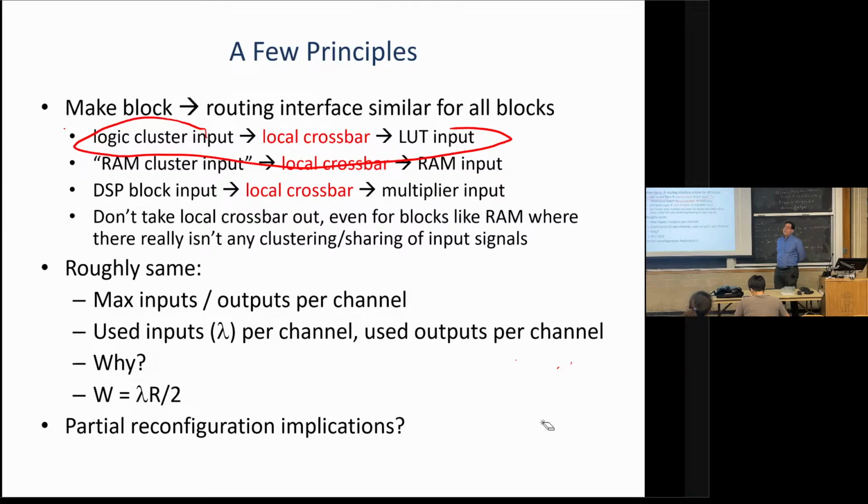So is there any downside to this second solution you came up with? The downside is that you've added a LUT. Adding a LUT costs you a bit of area and a bit of delay. But it's just one LUT, and usually your interface is not that big compared to what's inside. It does mean that you shouldn't be partially reconfiguring tiny things. It also adds a little bit of delay, which makes a stronger case that you should really register on this boundary, but that's best practice anyway.